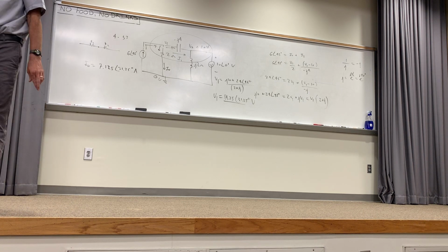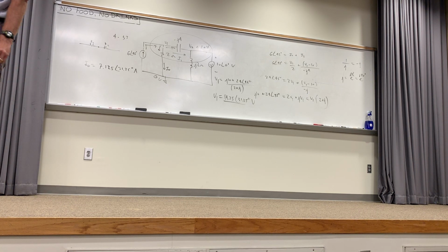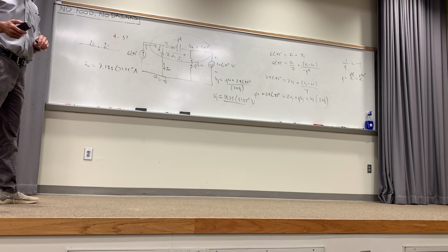So that bottom portion would be one node, not 2 nodes, because the bottom portion is ground, right? You don't ever think of it as a node per se because it's a single voltage, but our equations are written with respect to that being 0 volts. You never put a non-zero voltage there. Nodes usually have non-zero voltages, but we're setting that ground up arbitrarily.